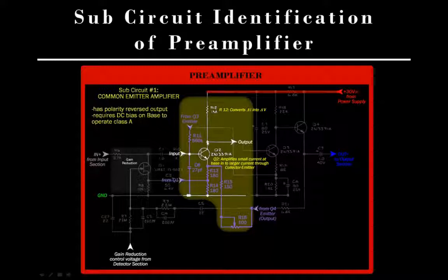Oh, we should start with identifying the subcircuit. So we have our input coming to the base, straight from our input to this subsection of the circuit. Our output goes, well, how do we know where our output goes? We have some more transistors here, discrete transistors. We've only looked at examples of circuits where the input is on the base. Common collector, common emitter, both have input going to the base. So the next transistor in line is Q3. Its base would be its input.